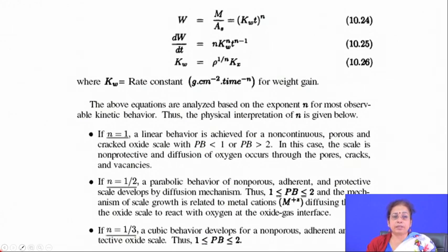On the other hand, if the diffusivity of the oxygen ion is much higher than that of the metal ion, you will find that the film is forming at the interface between the oxide and the metal. So, the way the film will form in case of oxidation which shows parabolic behavior depends on the relative diffusivities of the elements which are participating in the reaction.